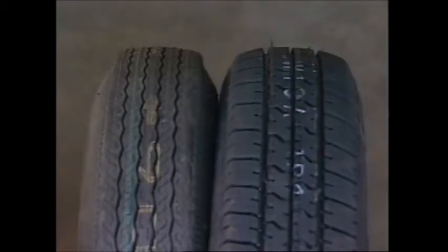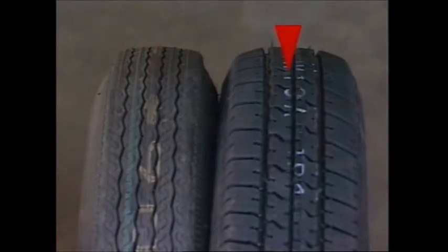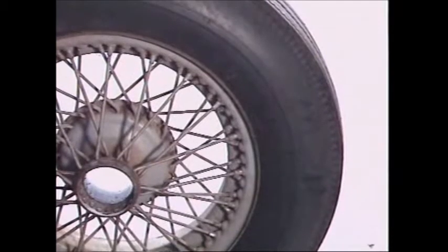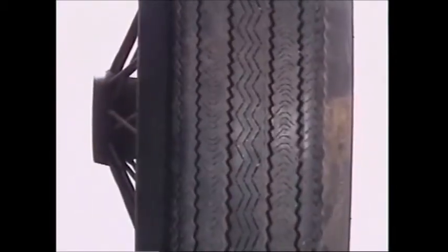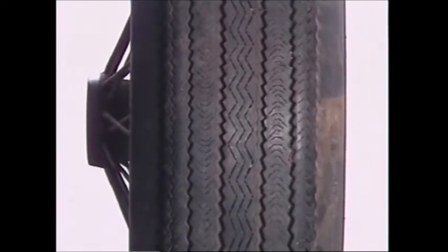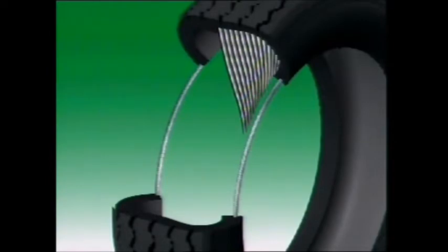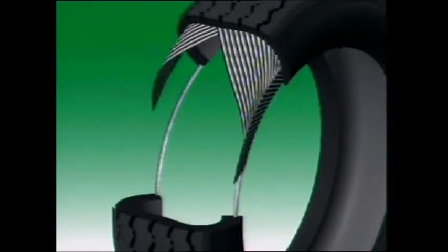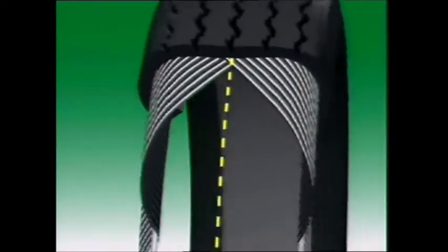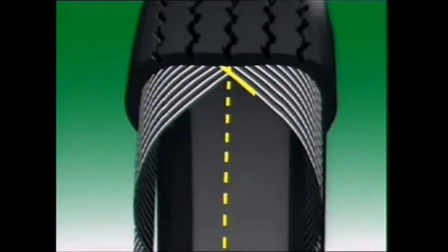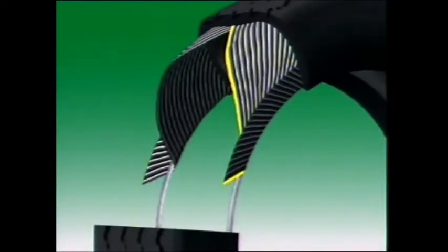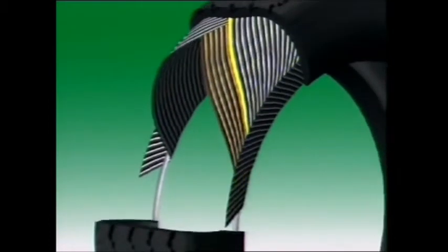Two types of tyre construction are common: cross-ply and radial ply. The cross-ply tyre is the older form. It is also called a bias ply or conventional tyre. It is constructed of two or more plies or layers of textile casing cords positioned diagonally from bead to bead. The rubber-encased cords run at an angle of between 30 and 38 degrees to the center line, with each cord wrapped around the beads. A latticed criss-crossed structure is formed, with alternate layers crossing over each other and laid with the cord angles in opposite directions.